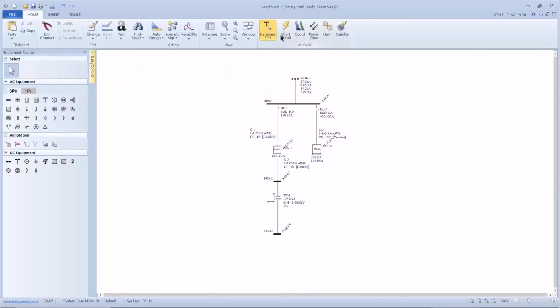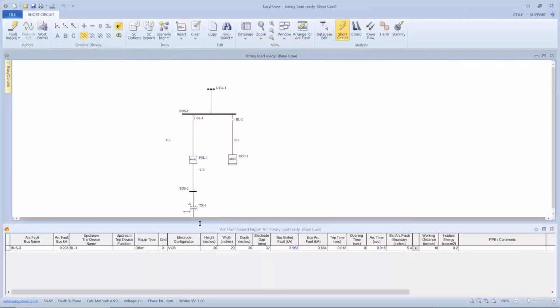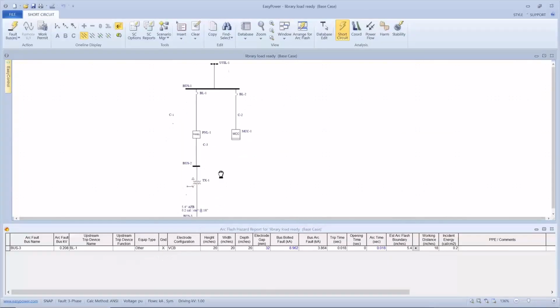All right, let's go back to short circuit, fault the bus. And now if we look at the tripping mechanism for this one bus, it'll indicate the feeder, or at least whatever upstream breaker is tripping, and to make sure it's correlated, we'd want to size the breaker inside the feeder on this panel, so this is tripping before our main feeder breaker is going to trip on the fault. Okay. Hopefully that was helpful. Thank you for the question.